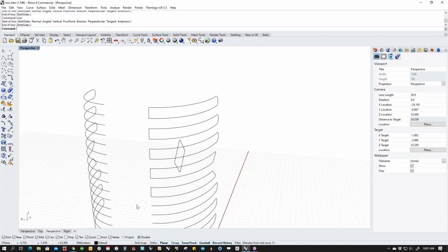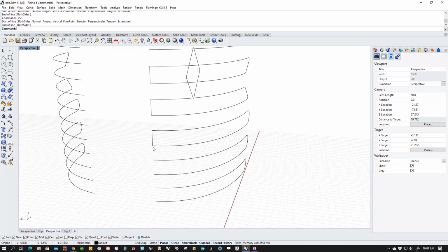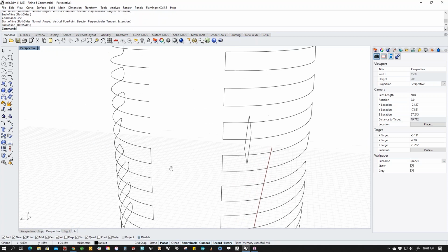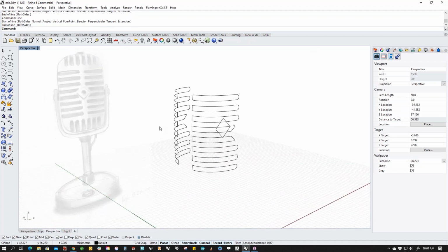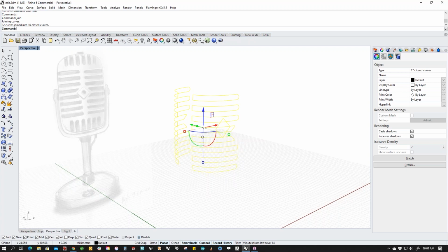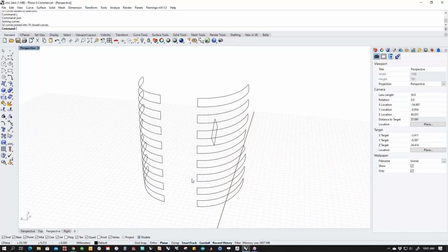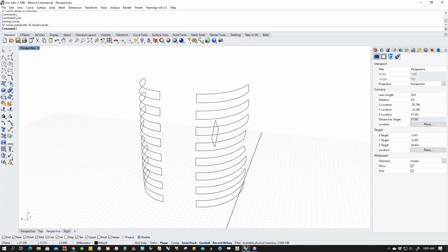Line is nice because it only asks for one line, whereas polyline makes you do one extra click, and that's how fussy I am about not having extra clicks. So line just wants 2 inputs and it finishes itself, whereas polyline, it's 2 inputs plus an enter. That's how you get fast, folks. Pay attention to that stuff. It's also how you avoid having repetitive strain injuries on your wrist.